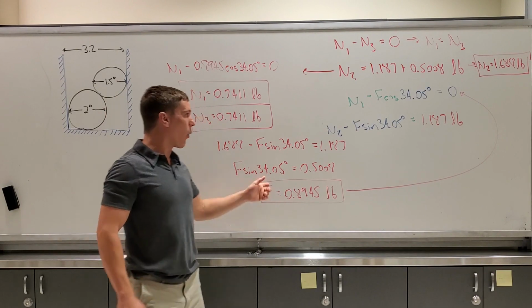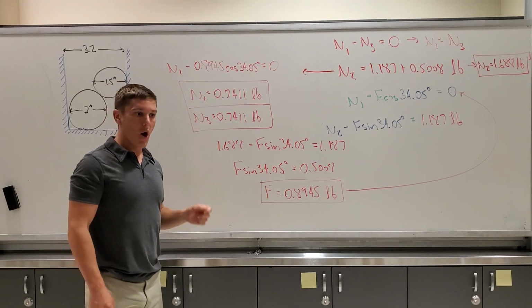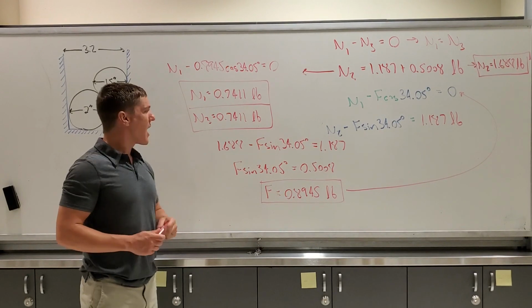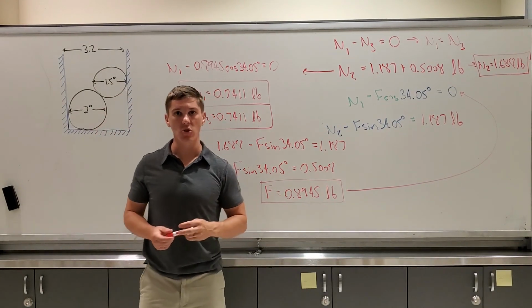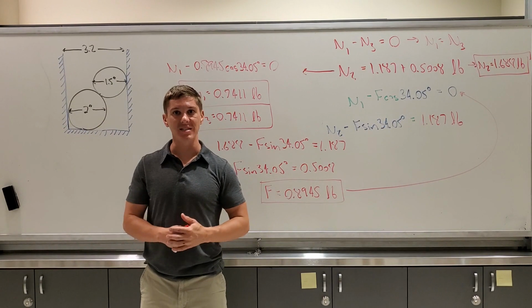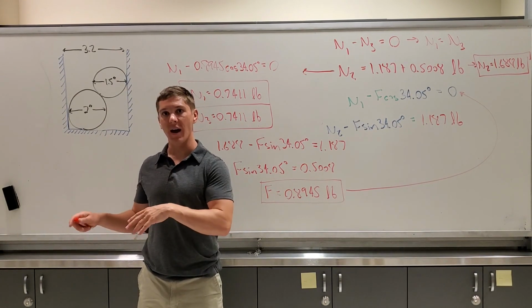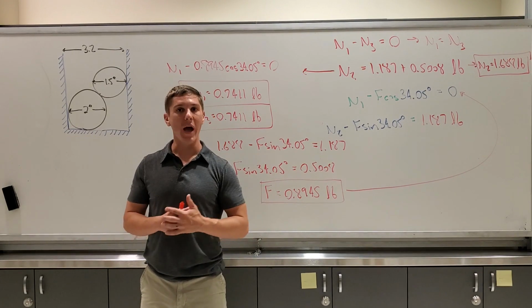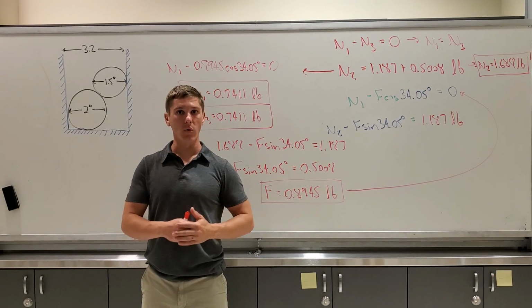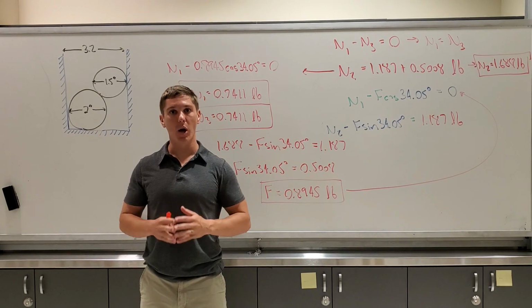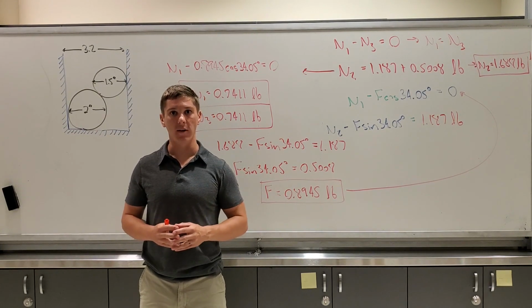The big thing I wanted to illustrate from this problem was how we can determine what our 4 equations were from 2 particles, and then I also wanted to make sure everyone understood the whole linearly independent side of this problem. It's really easy to think, okay, I can draw 3 free body diagrams and get 6 equations, but you actually cannot. For particle equilibrium, you can only have 2 times the number of particles. That's the maximum number of independent equations that you can find.